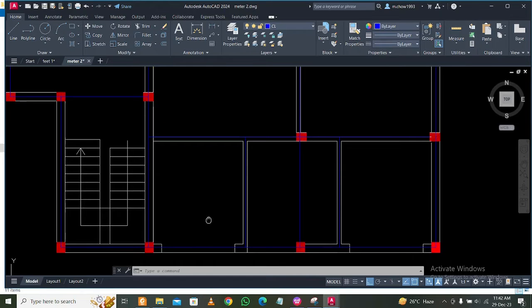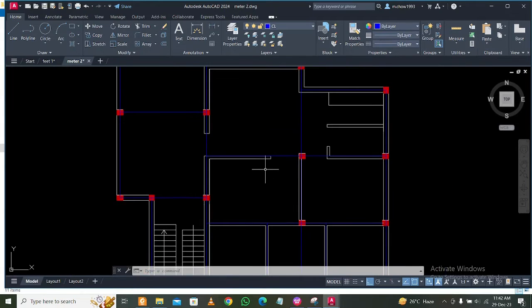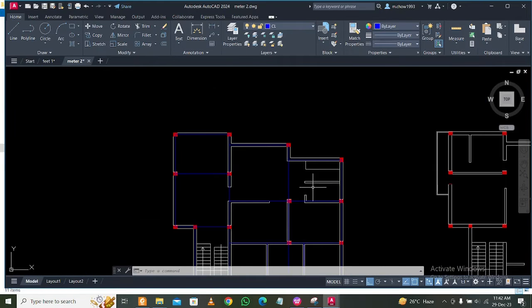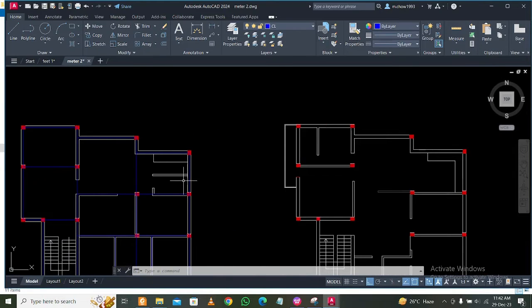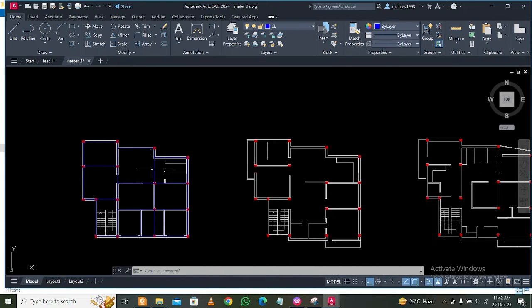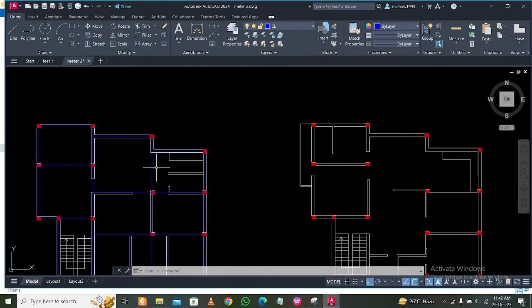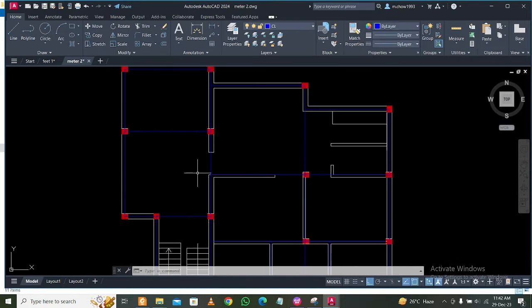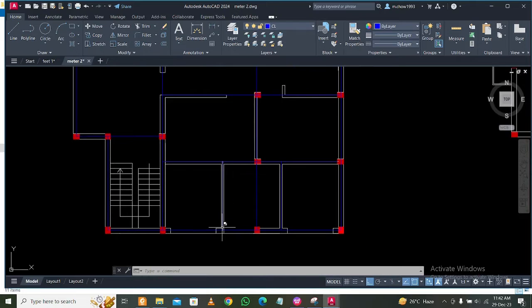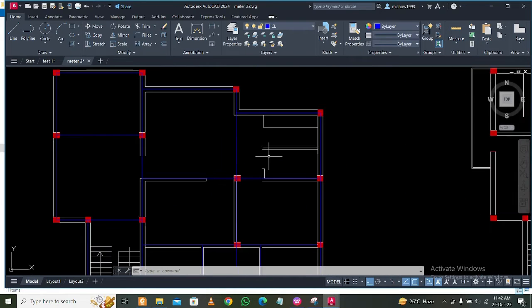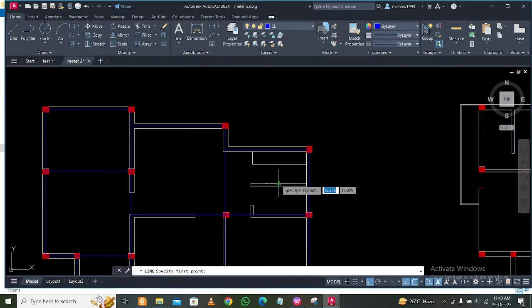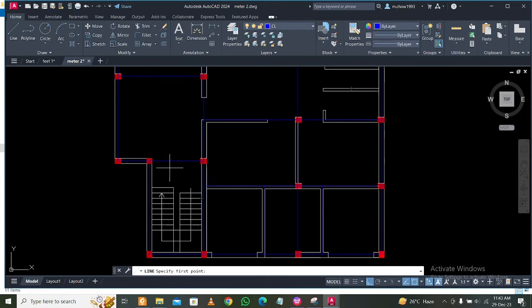Okay. So this is the zone. Here I think these are done, and these are done. And should I give this? I don't think this will be required, right? This is a plinth level, so at the plinth level we can ignore some beams, so this obviously won't be required. Since there is a wall, but the BCC, this won't be required. But if you want to give it, you can. You have some decent spacing, I think, in this layer.